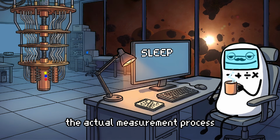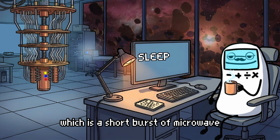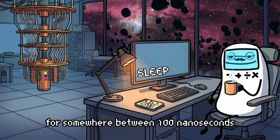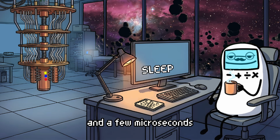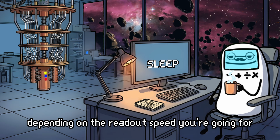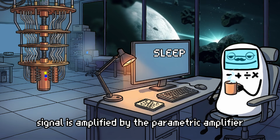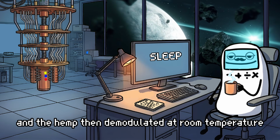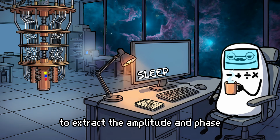The actual measurement process involves sending a readout pulse, which is a short burst of microwave at the resonator frequency, for somewhere between 100 nanoseconds and a few microseconds, depending on the readout speed you're going for. The reflected or transmitted signal is amplified by the parametric amplifier and the HEMT, then demodulated at room temperature to extract the amplitude and phase.